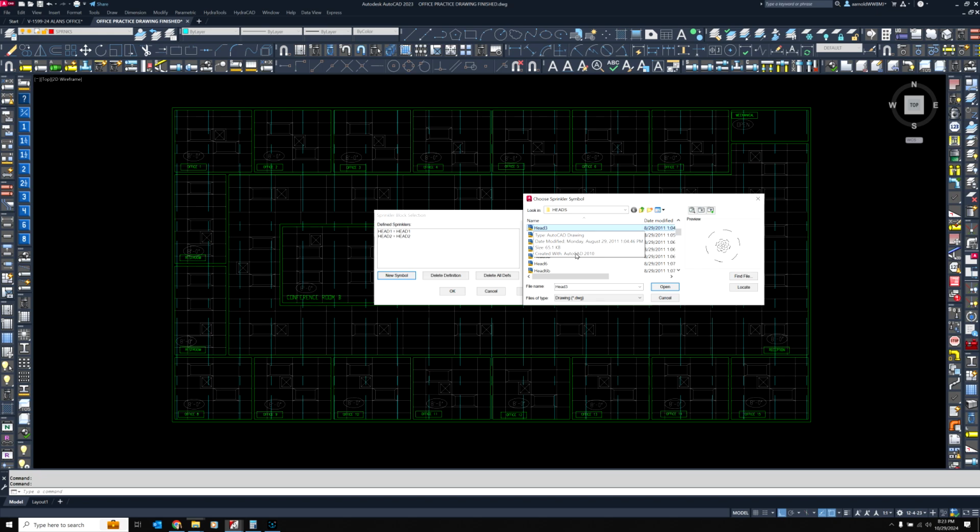That is our symbol for existing sprinkler heads. That is the standard symbol for an upright head, like we're going to put in our mechanical room in this building. This is the normal symbol for a pendant sprinkler head. In this case, it's going to be a recessed or semi-recessed. If you hear somebody say recessed sprinkler head and semi-recessed sprinkler head, 9 times out of 10 they mean the exact same thing. So right now, the bulk of what we're going to insert is this recessed sprinkler head symbol.